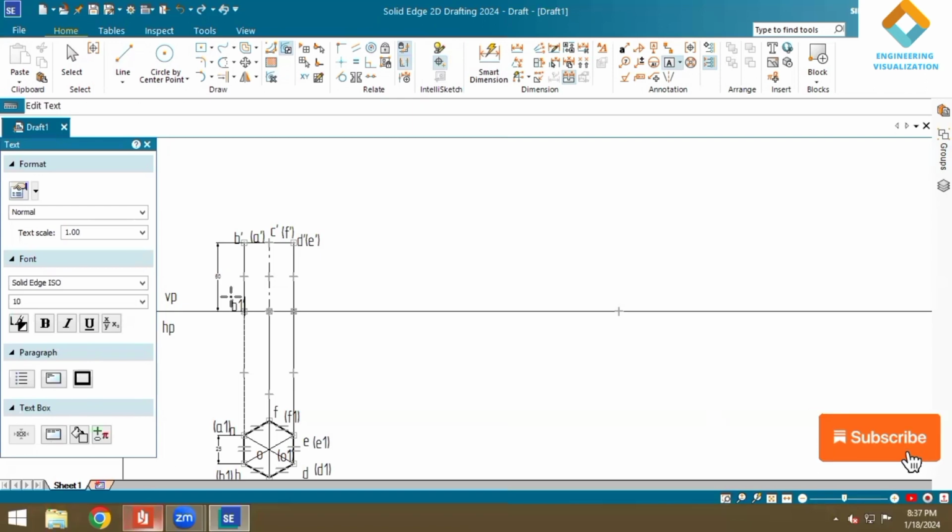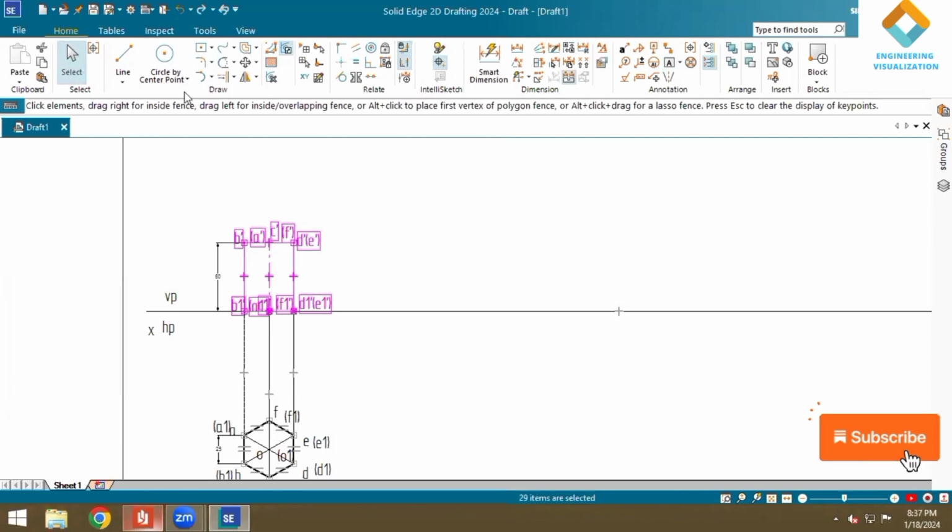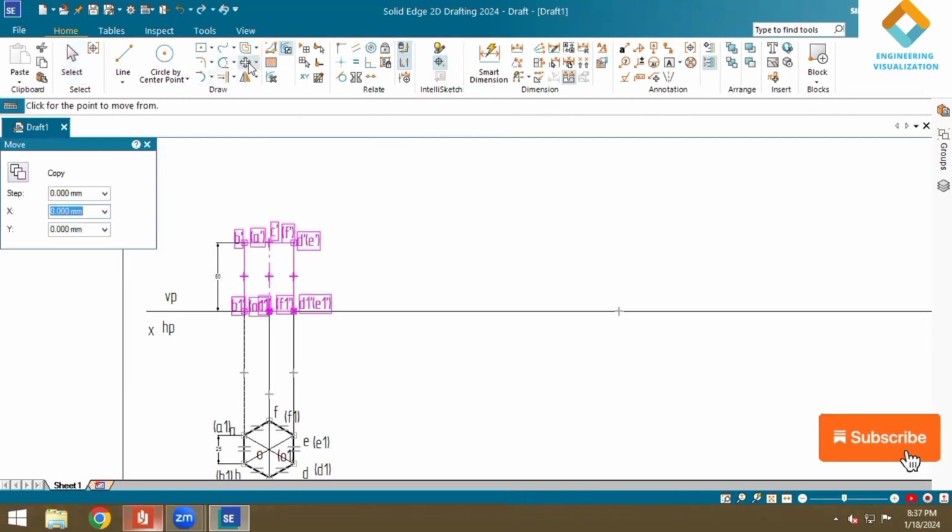Write down the front view notations. Those which are visible are written normally, and those which are not visible are written within brackets. Now select the entire thing, use the move command, create a copy and drag it along the XY line.